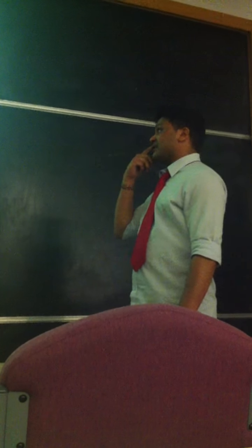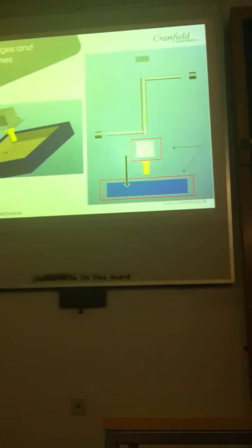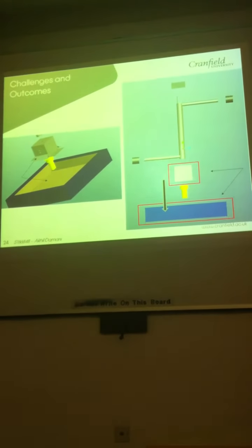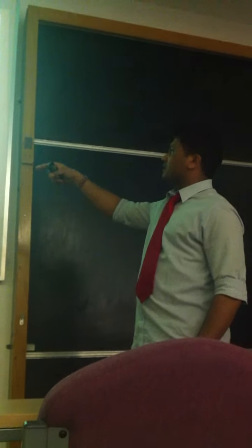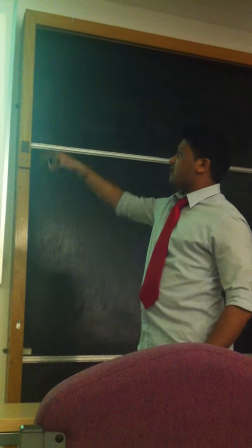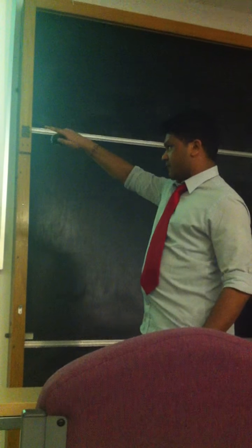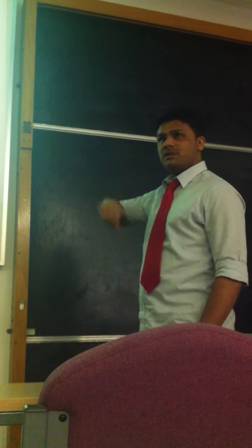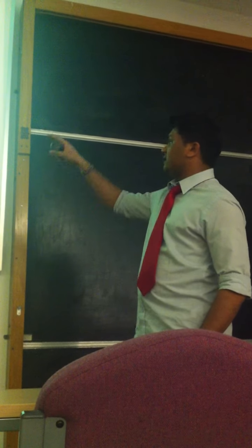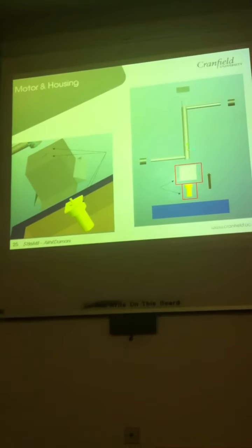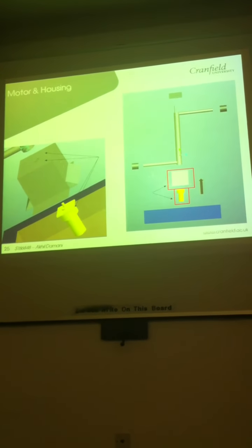There are a few design constraints. Initially, the base of the pod is quite thin, it's only 4 mil, so to drill holes in there you'd risk its stability. Therefore, what we decided was to glue the pod to the housing. The lid of the housing is also removable, so we can place the motor inside. The motor is then fixed onto the lid via the fixing holes, and the lid onto the housing via clips on the sides of the holes.